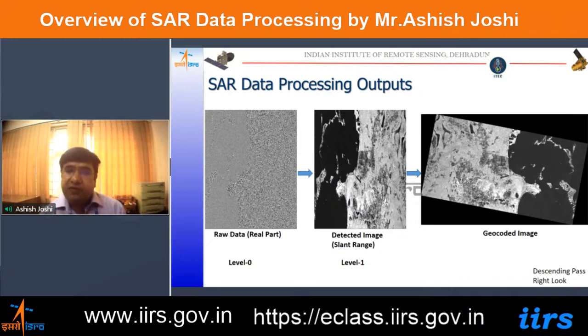In the geolocation, for every image pixel, we have to calculate the latitude and longitude using three equations: first the range equation, second the Doppler equation, and third the ellipsoid equation. These three equations can be used for SAR geolocation. After doing the SAR geolocation, we have the ij position and the lat long of this position. So for each image pixel we have some lat long, but still the image is not sampled to the geographical plane.